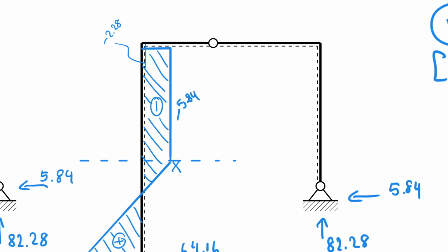And then I go down by 40 for every meter, right? So I go down, down, down, down, down until I hit the hinge, because that's where the evenly distributed force ends. And if I go down with 40 over that distance, I end up as minus 82.28, right?